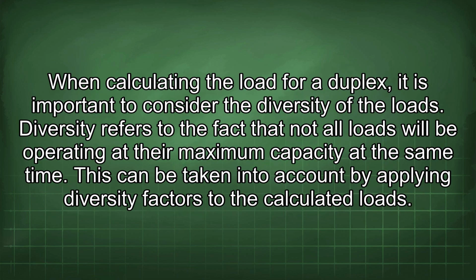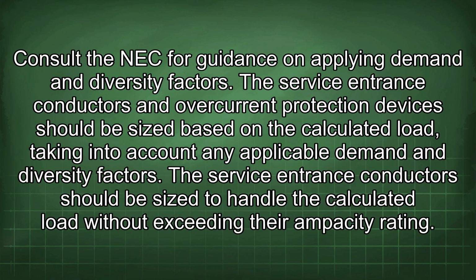When calculating the load for a duplex, it is important to consider the diversity of the loads. Diversity refers to the fact that not all loads will be operating at their maximum capacity at the same time. This can be taken into account by applying diversity factors to the calculated loads. Consult the NEC for guidance on applying demand and diversity factors. The service entrance conductors and overcurrent protection devices should be sized based on the calculated load, taking into account any applicable demand and diversity factors.